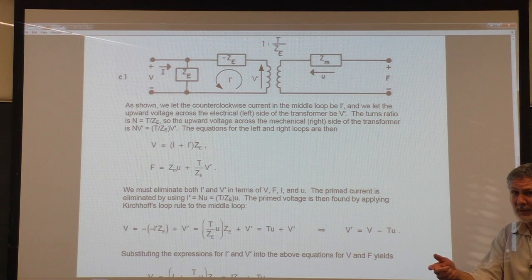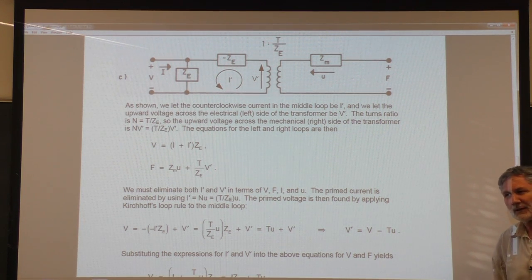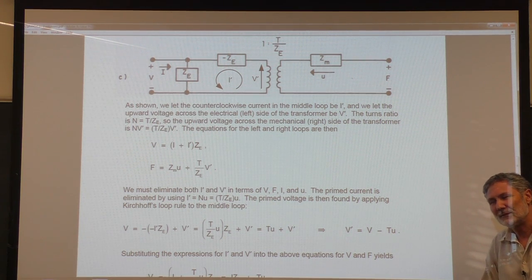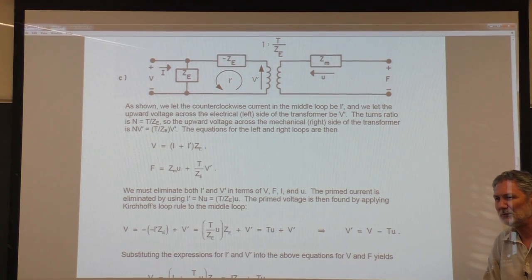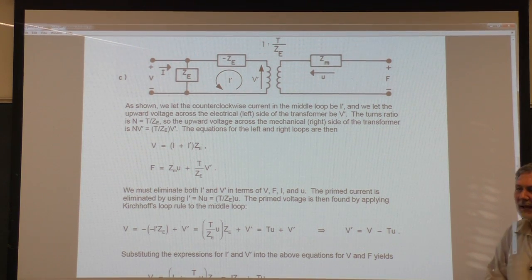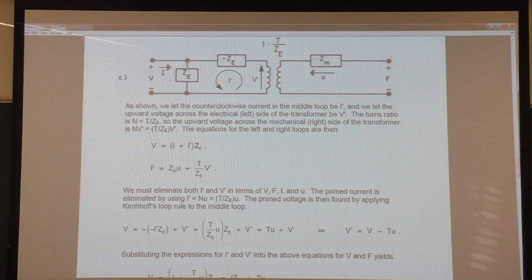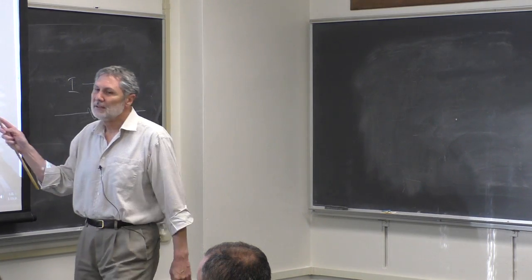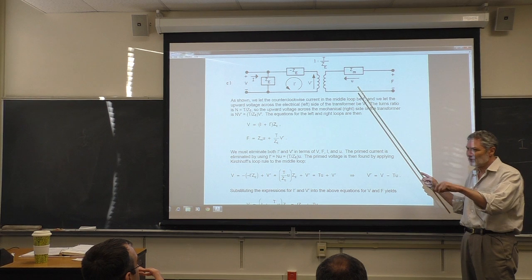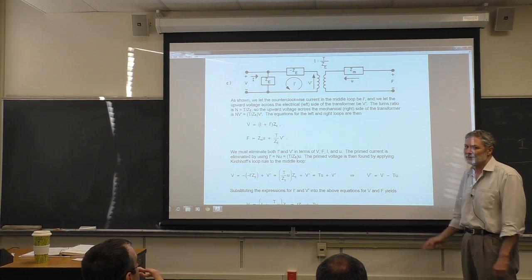So you get the same answer, right? We all agree? However you want to handle this, I have to admit, I like this drop idea. I like to not deal with these negative signs. But like I told you, when I get into trouble, I go through and very carefully sum all the voltages with plus and minus signs and set it equal to 0.